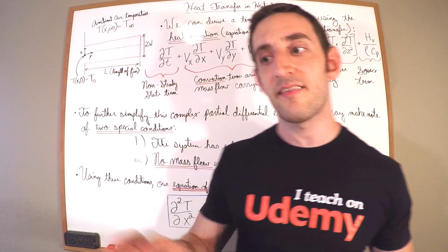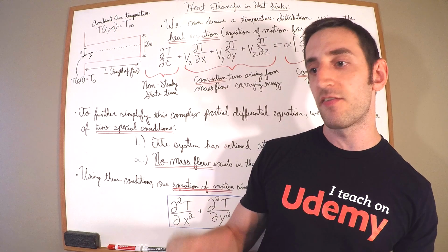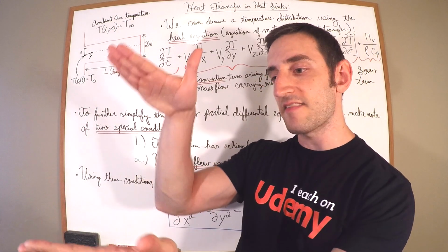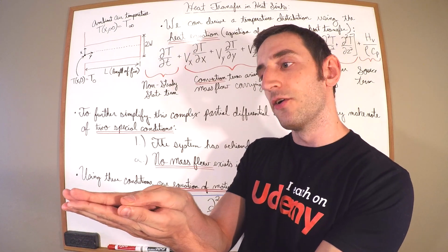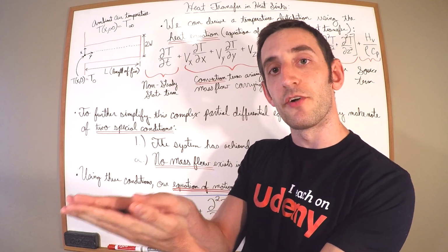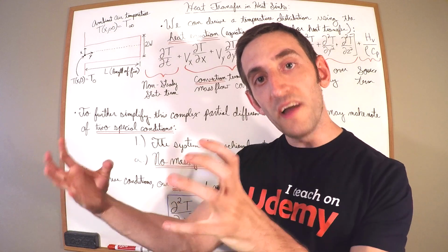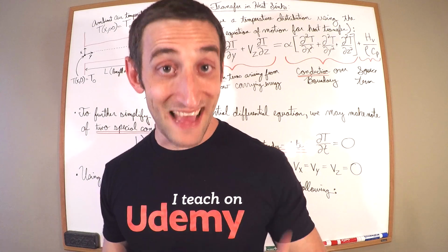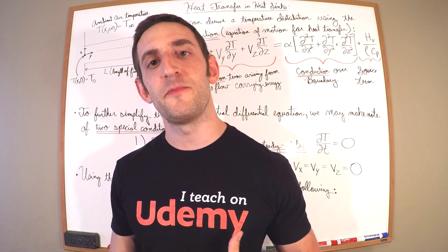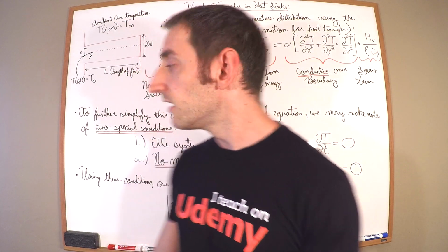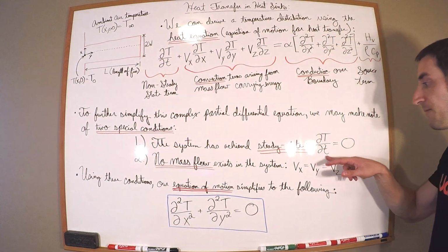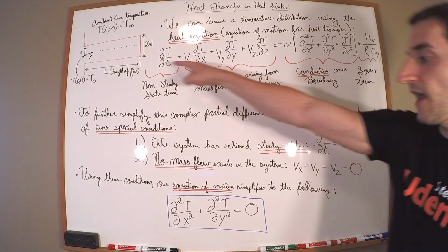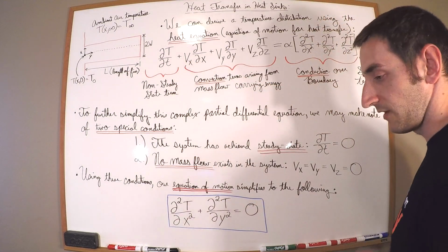We're going to assume that, let's say, we put up an application that consumes the same amount of energy at a constant rate, and that sets the base temperature of the base plate of your heat sink, that one temperature, and nothing changes. So in that kind of scenario, in steady state, the temperature distribution is not dependent upon time, and that allows us to say that the partial derivative of the temperature distribution with respect to time is 0, and this guy right here is going to pop off, okay?